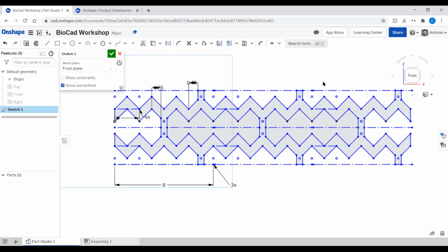Because you could do it both ways, right? You could pattern it out and then mirror it. The issue is, if you mess something up on the top, now it's messed up all 3 times. Whereas if you mess something up on the mirror, you can just change the mirror and then it'll reflect on the bottom too. I'm not sure if that answered your question.